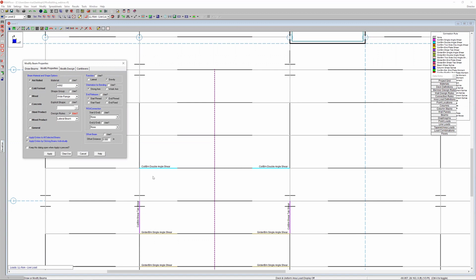In this case, we're not going to apply too many different connections. We'll also look at assigning some connections in RISA-3D. But I just wanted to show you that even though I'm not going to transfer directly from RISAFloor into RISAConnection, I'm going to go to RISA-3D. Because this model is one model, and this RISAFloor model is the place that this all starts and lives, we're still going to have that transfer of data, whether it's the load case information, the loading information, or the connection rules. That information is going to follow us from RISAFloor into RISA-3D and then finally into RISAConnection.